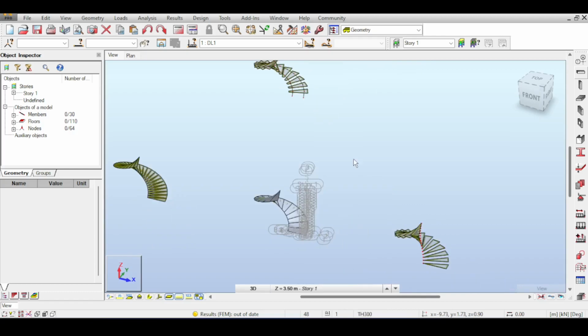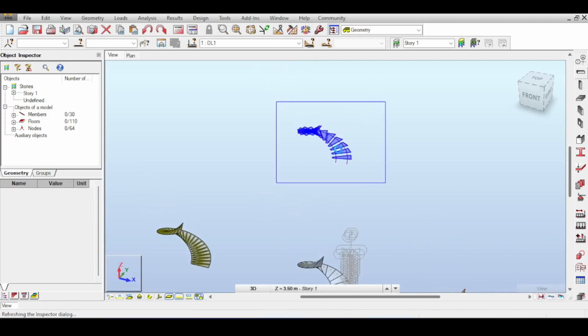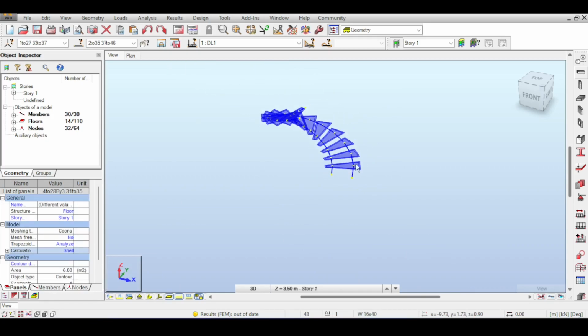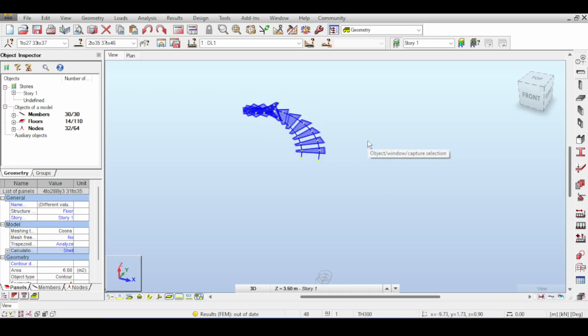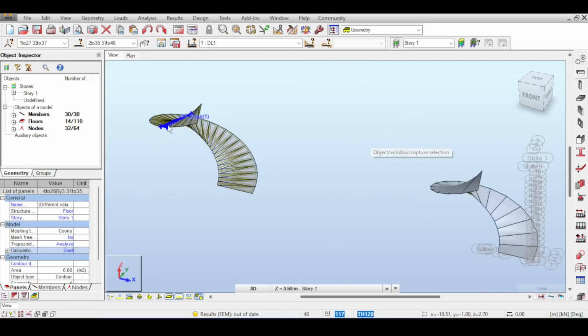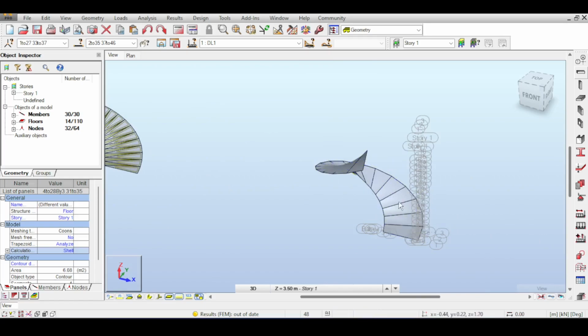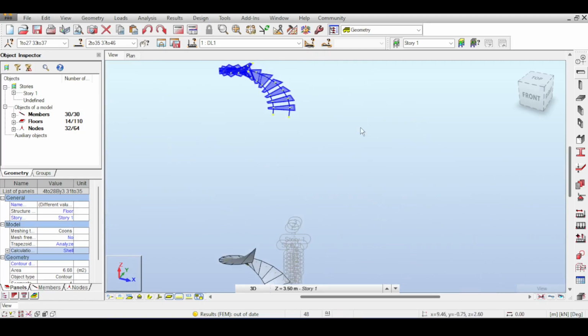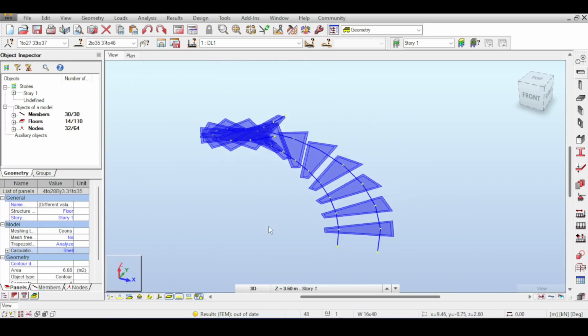Also notice that the staircase tread and riser here is already included because there is no riser. The riser itself is a gap. So you need to be careful exactly where to apply. It's not just like we apply forces willy-nilly. We actually need to take a step back and think where I should apply the dead loads as in risers and treads or not. Here it's applicable because the riser and tread was not modeled. Here it's applicable because the riser and tread was not modeled. Here it is not applicable because the riser is a gap and the tread is already the steel plate, similar to here. Of course, you might have covering materials and you might have rails, and I will leave the application of rails for you.